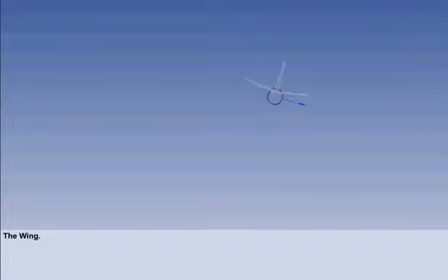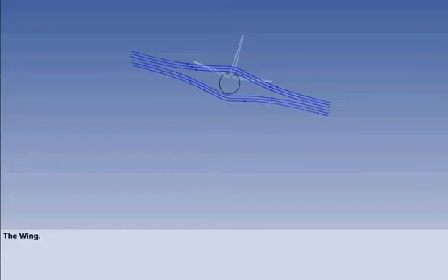As the aircraft side slips, the relative airflow is from the side, which we can replace with a view of an airflow stream. We can see that the airflow path is partly over the top and partly beneath the fuselage. This airflow is around the fuselage where the wing is attached. First, we'll look at a wing mounted on the bottom of the fuselage.